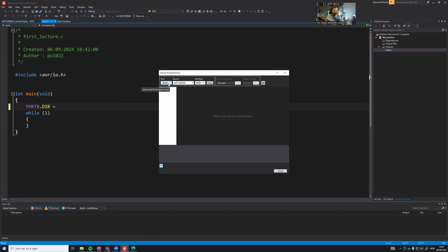It could be just a software problem with the Microchip Studio, but it could also be that your USB cable is not actually having any data traces, so it's only for power, which is quite stupid in my opinion. But anyways, that's how things work these days. Lots of equipment are bought with USB power.